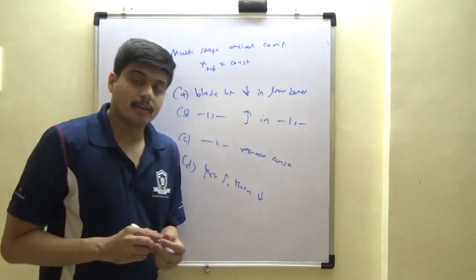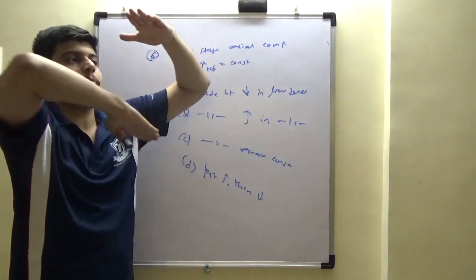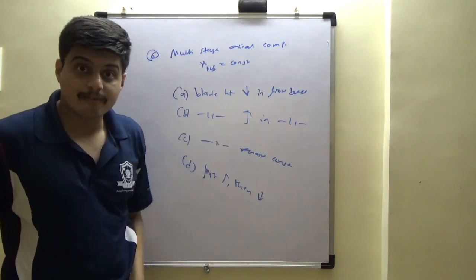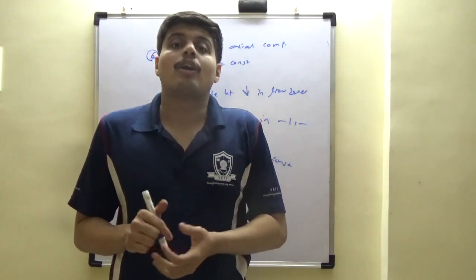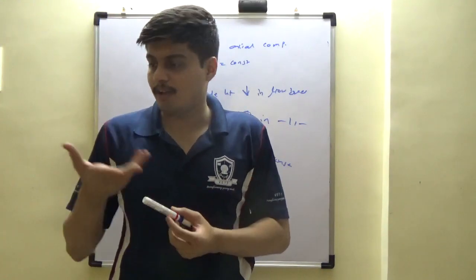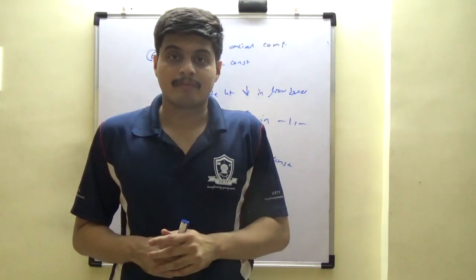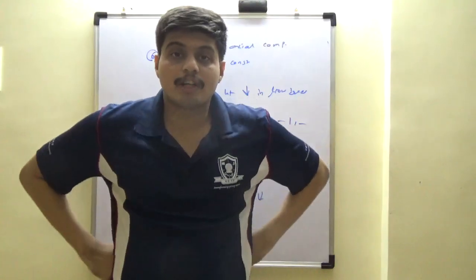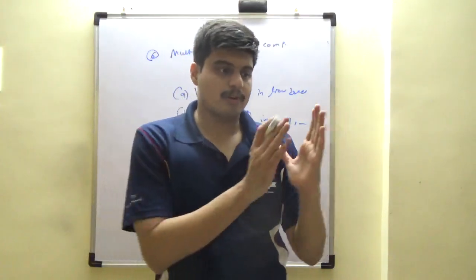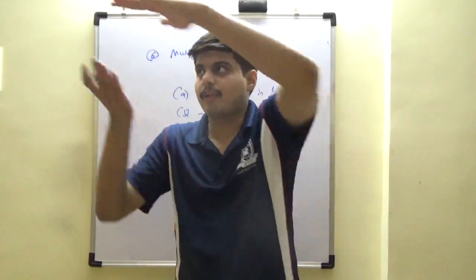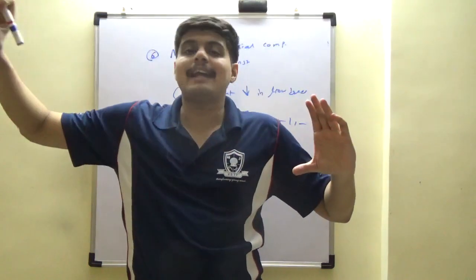If you remember my lecture, we had said you make hub progressively going up and the clearance between hub and tip smaller because as the pressure keeps building up, density moving up, rho A V, V is almost similar, relative velocity is not changing much. Area has to constrain to maintain the mass flow. Mass flow rate within the stage cannot change, right? M dot is conserved. M dot here before, just at the beginning of compression, is where the full compression is achieved. But look at the density change. So you have to reduce the area.